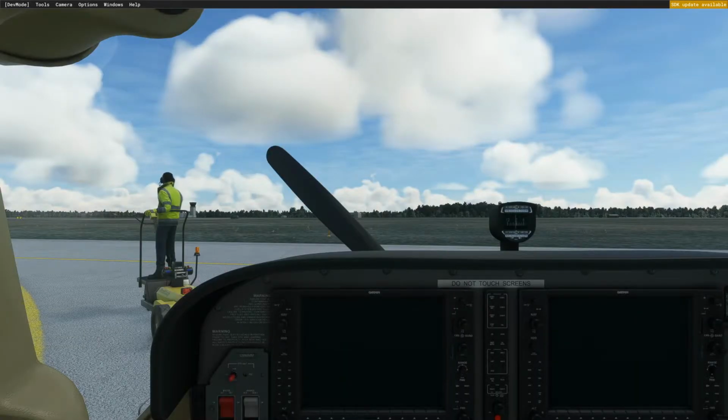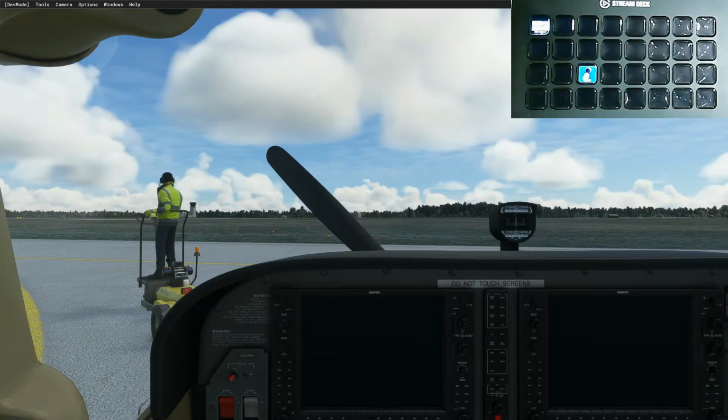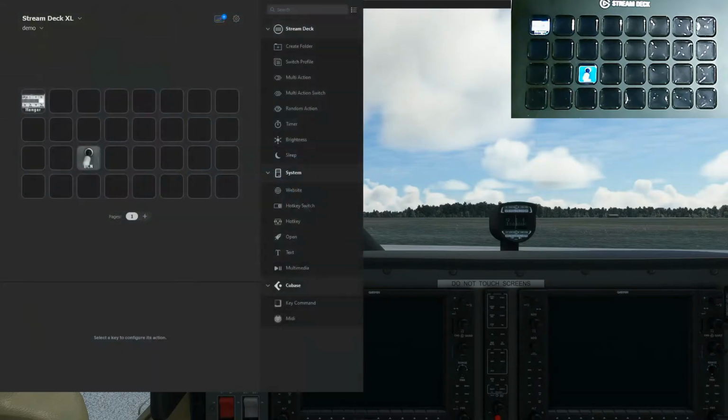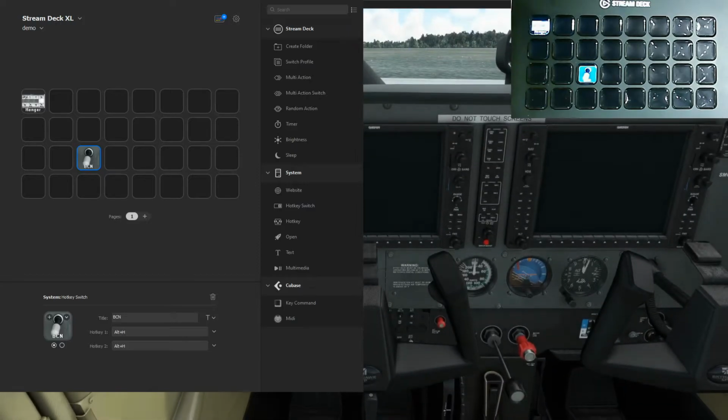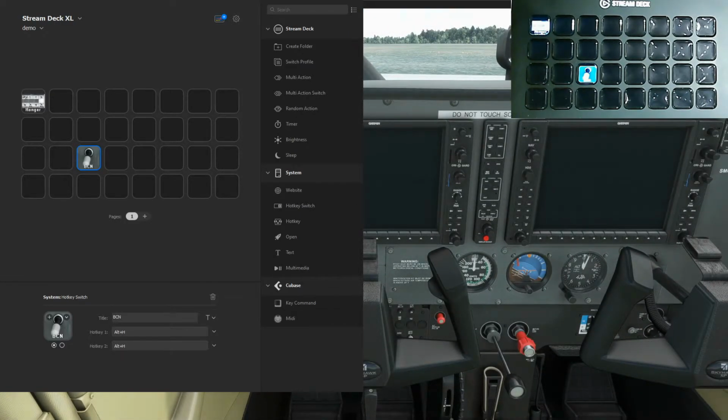We had the flight simulator up and running, and I had my Stream Deck, and we were programming it without X's and O's. And we got as far as using the Stream Deck software, and it was sending keyboard shortcuts, but it doesn't really work, because as soon as we lose focus, click on anything else, there's a tendency for the switches to get out of sequence. And also, there aren't enough keyboard shortcuts for the hundreds of possible commands that we can send. So we want to look at how we use X's and O's to overcome these problems.